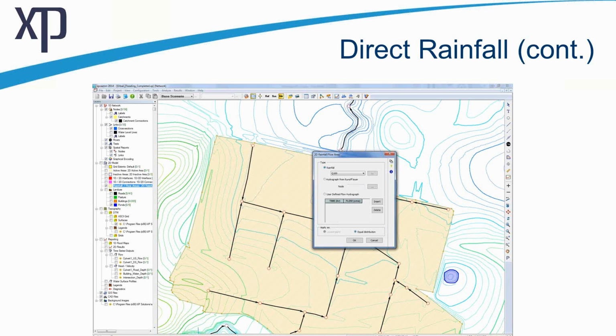And we can see here I've just drawn a simple polygon over an area, and where this orange shaded polygon sits is the area that I'm going to say rainfall will occur to assess the performance of what in this particular example is actually a minor drainage or pipe network system. From a dialog box we just simply need to say this is the rainfall I wish to occur in this zone, and I would also define other elements such as buildings, road land use characteristics, and then analyse the performance at the creek at the northern end of this site. So that's sort of the more recent change to hydrology.